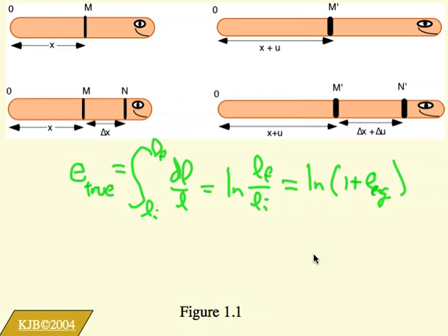So that's an example, that's the definition, that's how we define the strain. In this case, we define the strain in the x direction, so we might describe this as E_x, or you'll also see this described as the strain in the x direction for an initial segment of length x. In some cases, you'll see this described with people thinking of the x-axis as the one axis, and so this might be the strain in the one direction, or it could be written also more precisely as the strain for the stretch in the one direction along the initial length in the x direction, where x is the first one of the three axes defined.